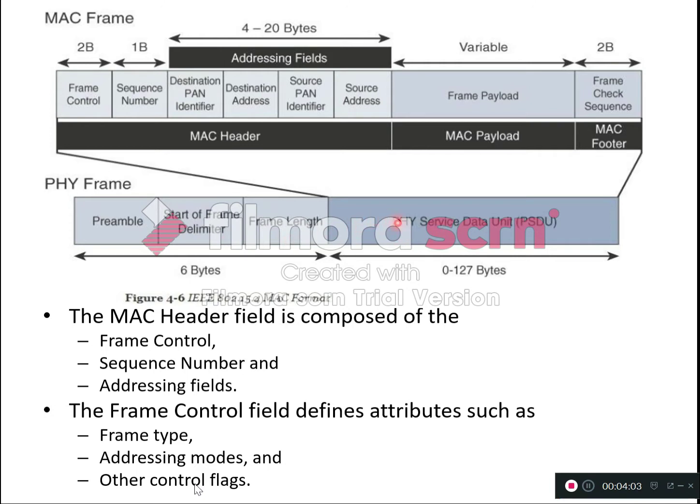So now what is the MAC frame format? The PSDU itself is the MAC frame. See, it is extending here. The PSDU full format is displayed here. So that itself is the MAC frame. So what are the contents of the MAC frame? Let us see. Here also it has a frame control, sequence number, destination PAN identifier, destination address, source PAN identifier, source address. So all these will make the MAC header, and these 4